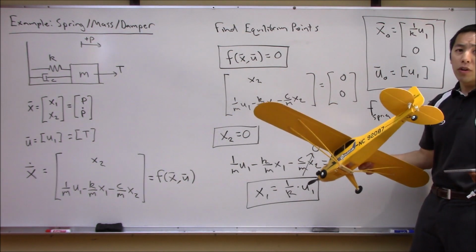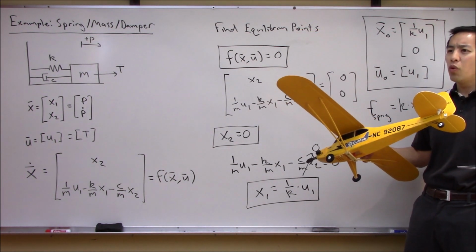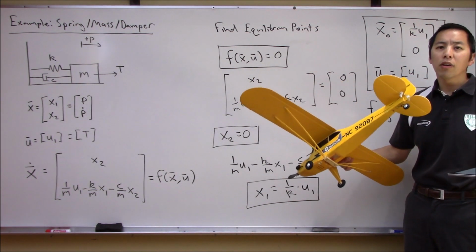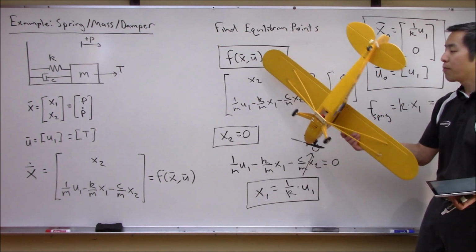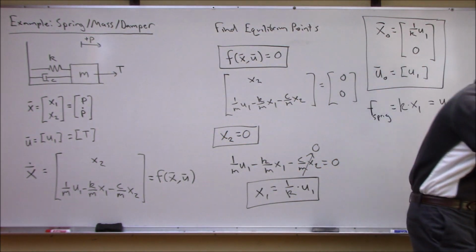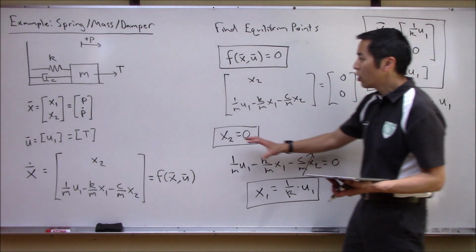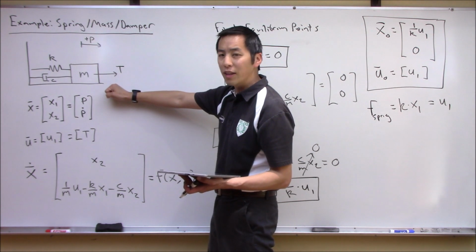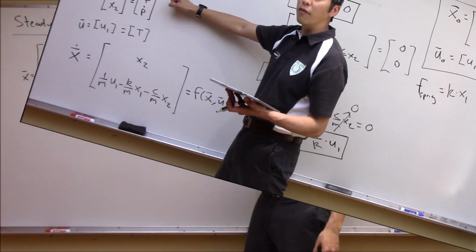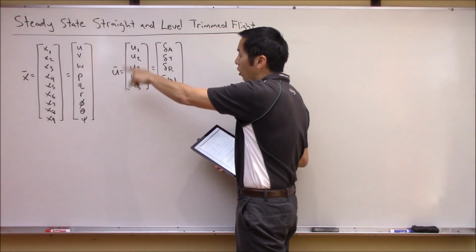So that's what I want to look at now. That's the intuitive way a pilot might do this, but as engineers, we don't want a system that requires you to go fly the aircraft. We want some sort of numerical routine that allows us to work with the mathematical model and find this trim point, rather than conducting costly, expensive flight tests. So with that being said, give me a second to erase the board, and let's think about what if, instead of this really simple example, we had our full 6 degree of freedom nonlinear RCAM 2-engine aircraft model. Let's now look at applying this idea to our RCAM model.